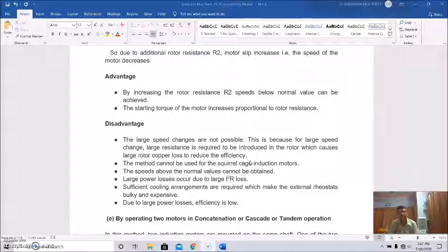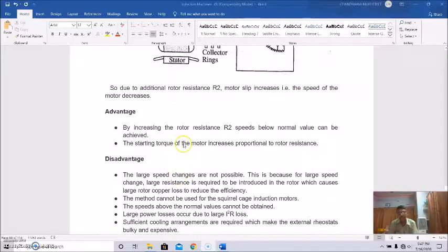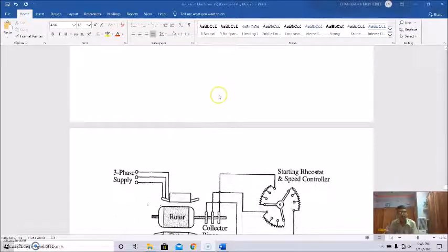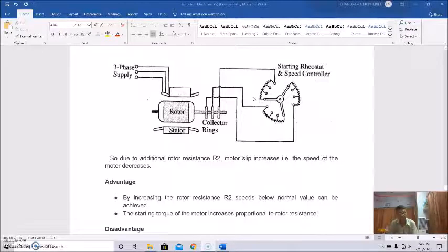So these are the methods which can be applied for speed control. One is the stator pole changing methods, either consequent pole changing or multiple stator windings, and then the pole amplitude modulation method, by another auxiliary MMF modulation wave, and as a result the pole can be changed. The resultant pole will be either the difference of the original MMF wave poles and the modulation wave poles, or maybe the summation.